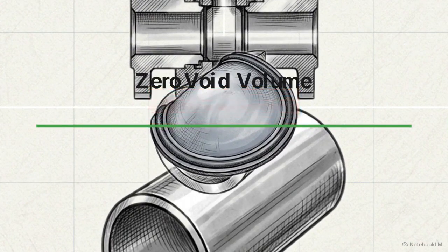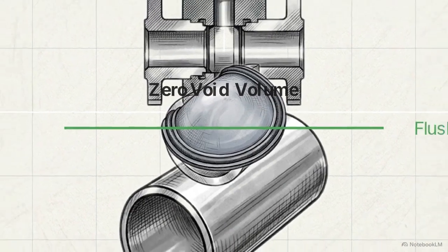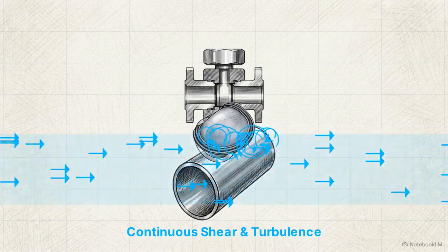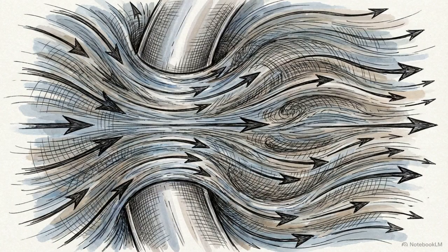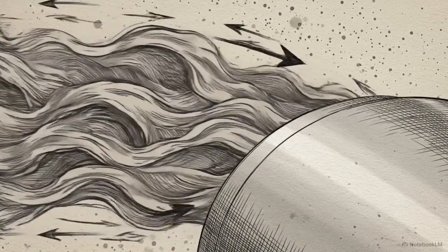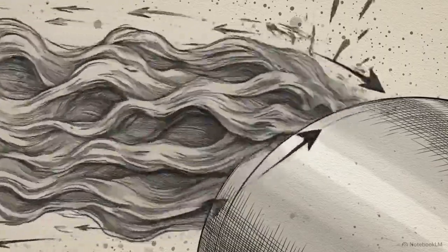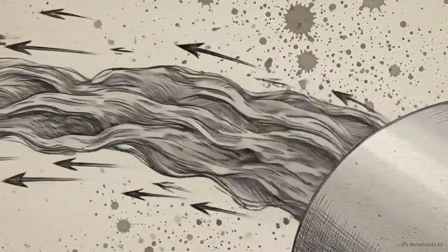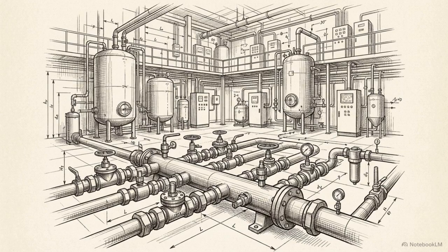This geometry dictates a state of continuous turbulence. The flow from the main pipe violently and continuously washes directly over the flush diaphragm and weir. The shear force of the main loop's velocity perpetually and actively sweeps the entire valve surface. There are no isolated pockets, and there are no stagnant boundary layers where velocity drops. This continuous sweeping physically prevents bacterial adhesion from initiating. The bacteria can never establish a foothold on the steel. ZDL architecture achieves absolute purity by utilizing the system's own kinetic energy to engineer an environment actively hostile to stagnation.